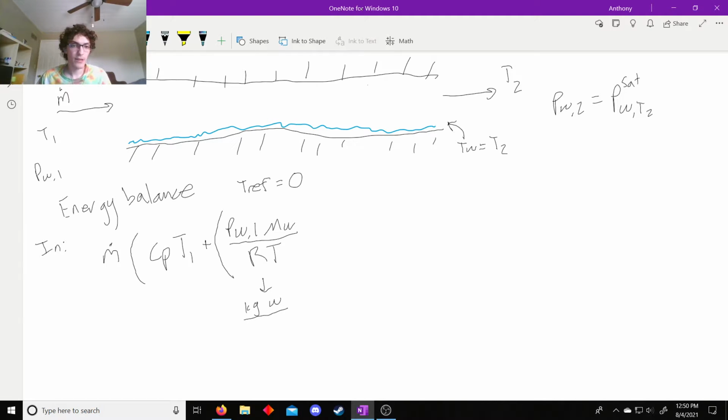divided by a volume of total air that's actually going in. And when I say total air, I mean total air plus whatever water it brought in with it. We'll call this meters cubed of total. But remember, we have this mass of air coming in, so we need to relate how much mass of water is in the air to the mass of air. Does that make sense?